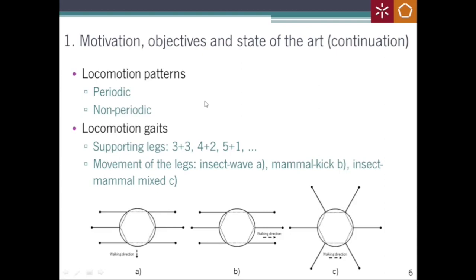Regarding the characterization of locomotion, a locomotion pattern is said to be periodic when the robot's feet are raised and placed on the ground in a repetitive manner, being the form with the least associated computational processing power. A locomotion pattern is said to be non-periodic when the robot's feet are placed in pre-selected locations, and as such it is a pattern that requires more computational power, being indicated for irregular terrains. For the present work, only the periodic locomotion pattern will be implemented.